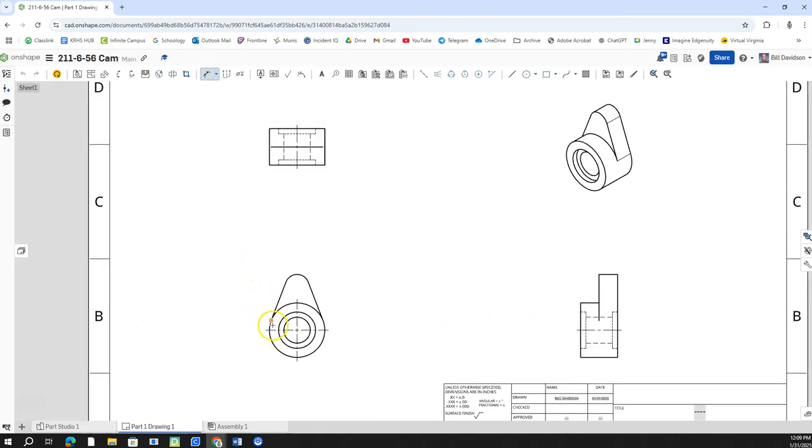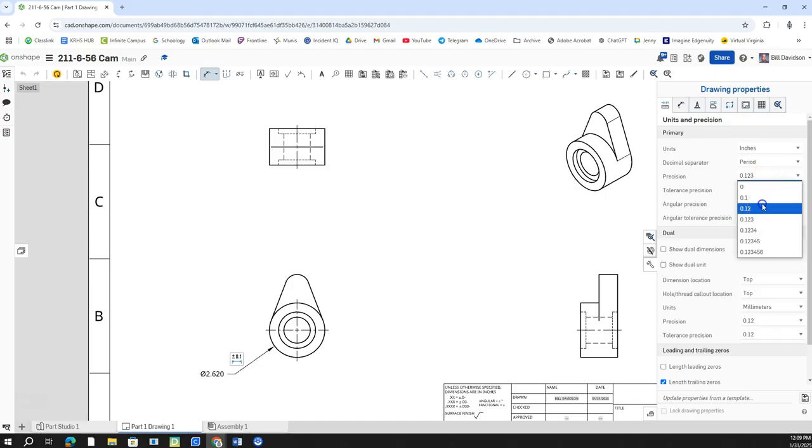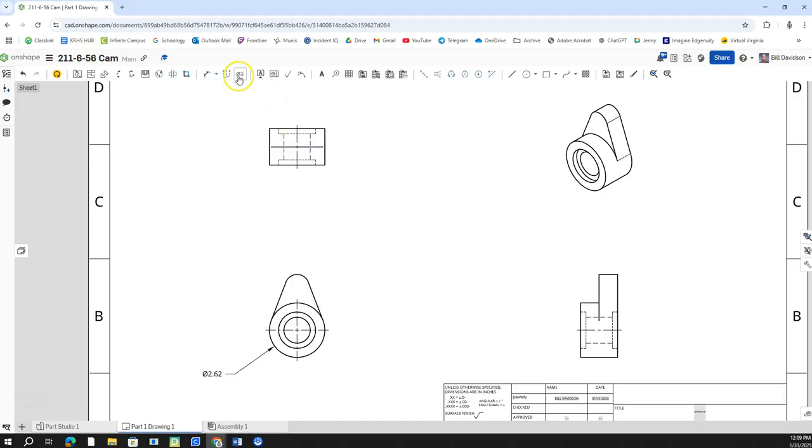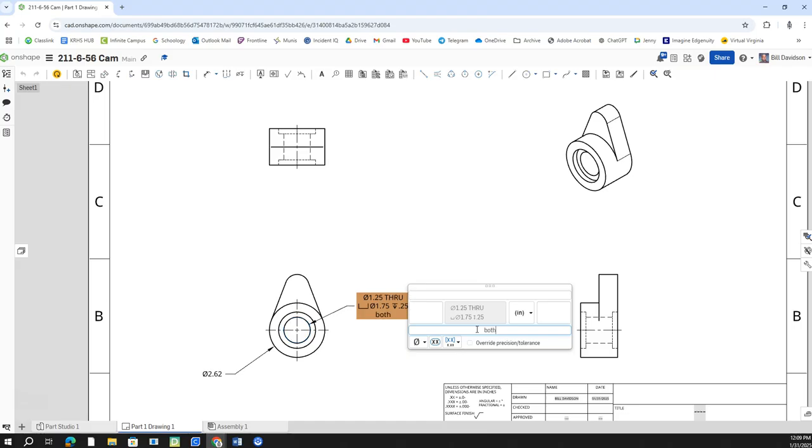I'll go ahead and click this diameter of that circle right there. I want to make sure that I use the hole command when I do this. Then I'll click the hole feature. Click that right there, and it tells us this. And so we will. I'm actually going to change this to say both ends like it did in the thing, so you're aware that it happens in both places. So you can see it now in the drawing that happens that way.